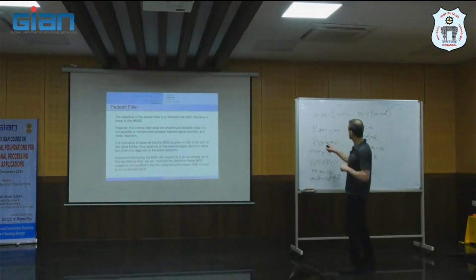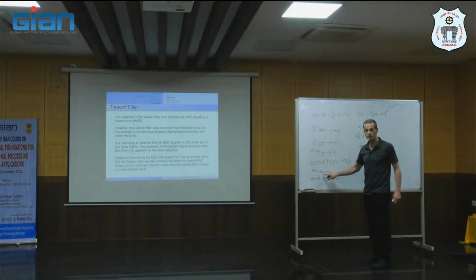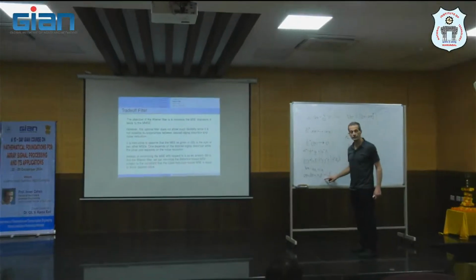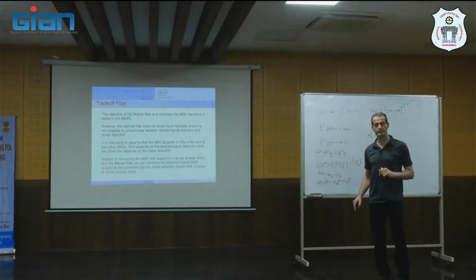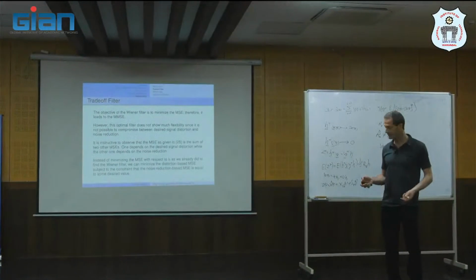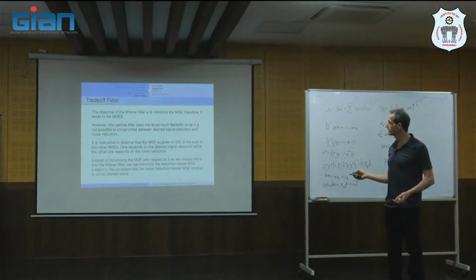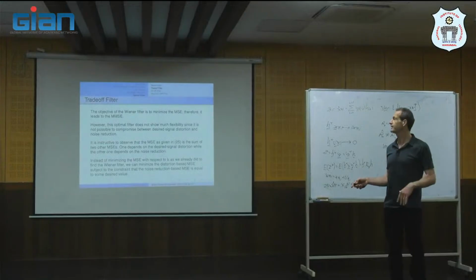It means that we want the filter-designed X to be equal to X, no distortion. And then we want to minimize the variance of the residual noise. This is the MVDR filter. And when we come to multi-channel signal processing, we will see the relation between the MVDR filter and the MVDR beamformer, or multi-channel MVDR. That's why we want to see it here.